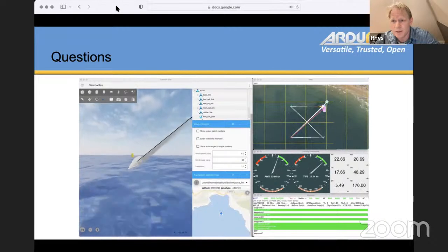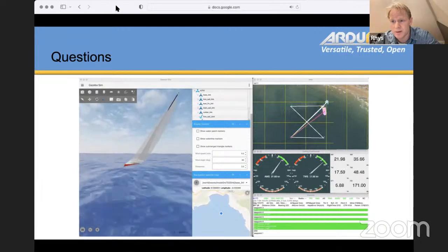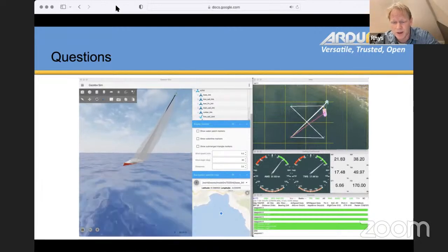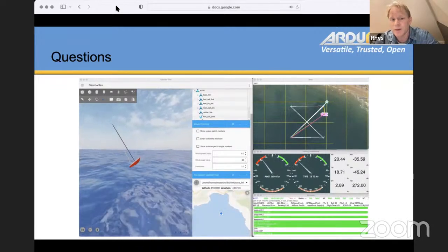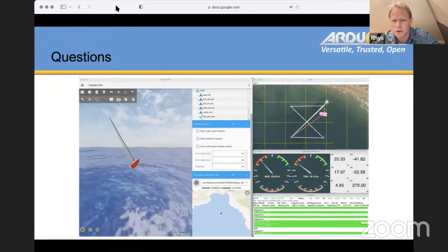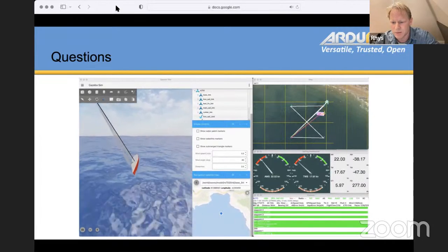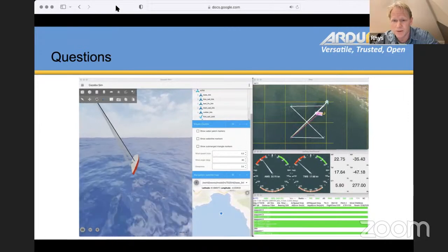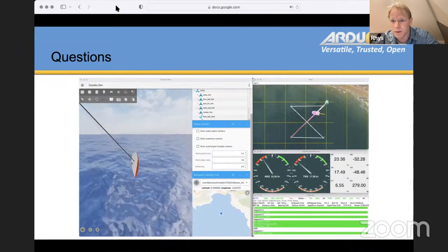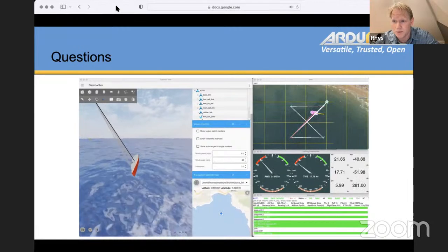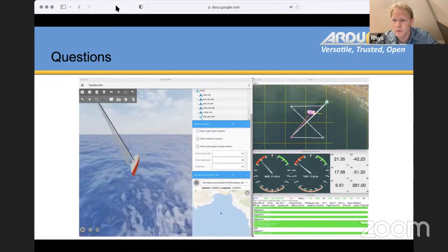They are configurable. You would need to have a look at the camera sensors that Gazebo provides and see whether they have enough fields for you to manage. You can control the field of view, aspect ratio, pixel count, and various other properties of the camera. If it didn't provide exactly what you wanted, then you'd have the option of writing a custom plugin to provide your own camera sensor, or modify one of the existing ones as you require.